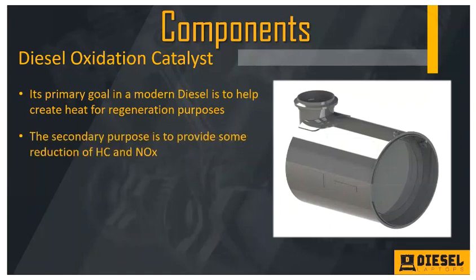Its secondary purpose when not in regeneration, because of the makeup of this assembly, is that it's also going to provide some reduction of hydrocarbons and NOx. Hydrocarbons and NOx are two of the things that this emission system's trying to break down and either modify or completely catch. So the DOC does have two functions. Again, it's going to reduce hydrocarbons and NOx slightly, but its number one goal is to create heat for regeneration